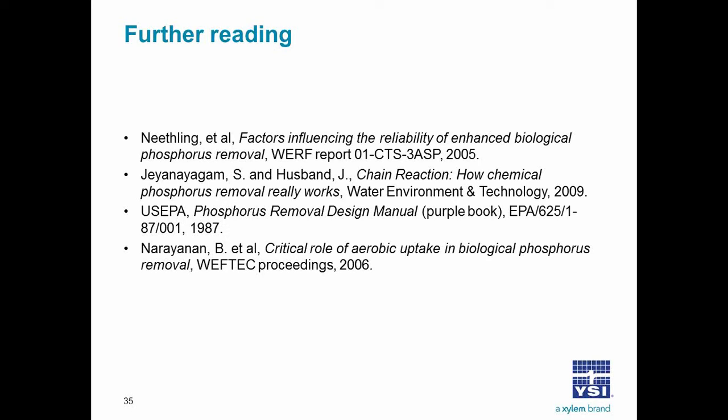Measuring the phosphate in the oxic zone will enable you to find out if the uptake is sufficient, but if you still have relatively high levels, you will need to also do some monitoring of the release, because if the release is not sufficient, the uptake will not be able to make up for it. I think that answers your question, but if it doesn't, please restate it or ask it again, and we'll try to address it.